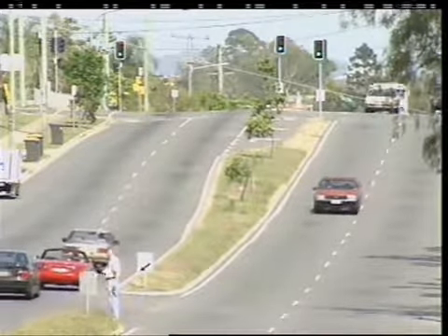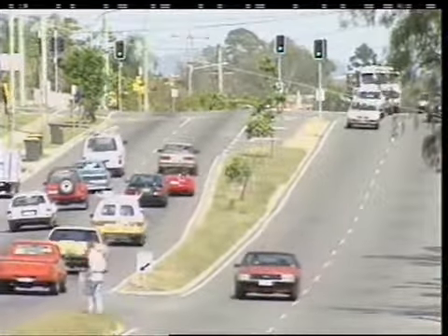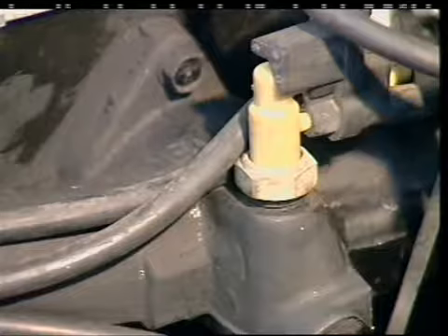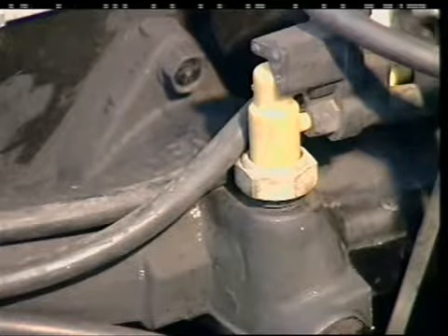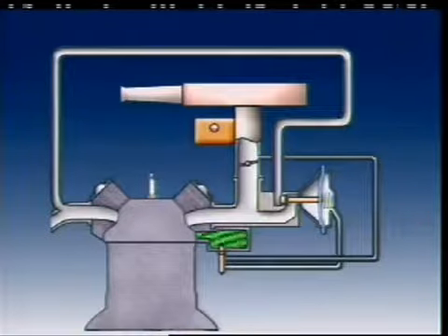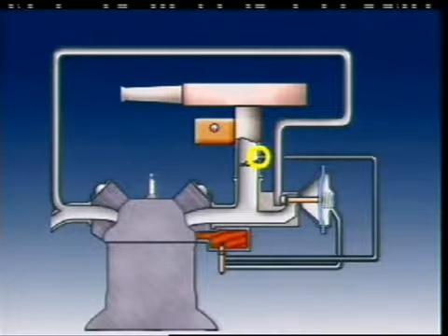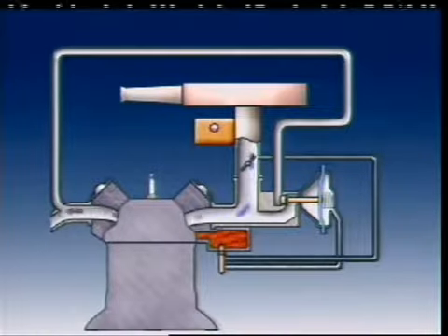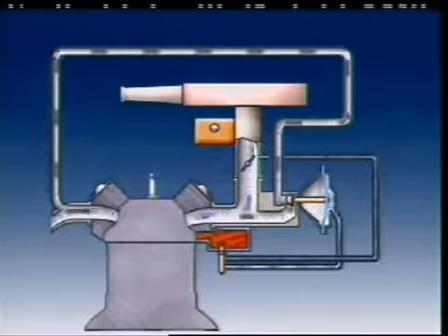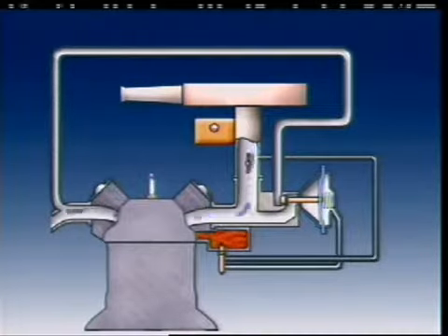The EGR valve usually opens when the engine is at normal operating temperature and likely to be using a lean mixture. When the engine first starts and until it warms up, a temperature-sensitive valve prevents manifold pressure reaching the EGR valve and stops it from operating. Manifold pressure reaches the valve when the engine is warm, and when the EGR port at the carburetor is influenced by the position of the throttle. This is generally at light throttle openings, when a lean mixture could cause increased oxides of nitrogen. It does not operate at idle or at wide open throttle.